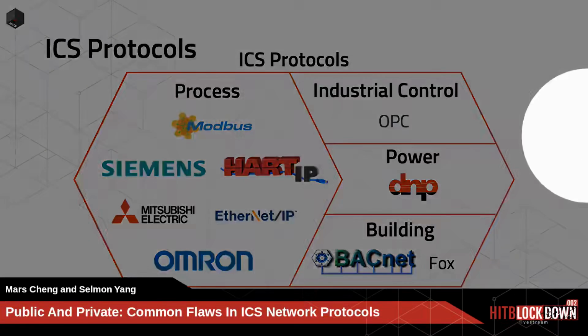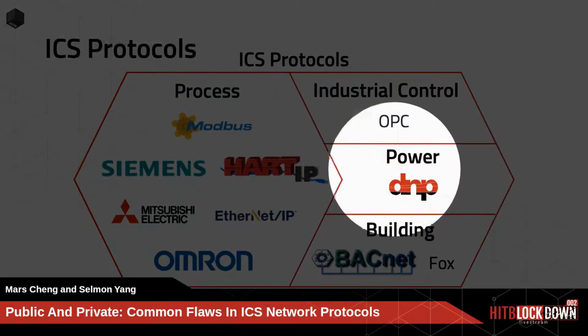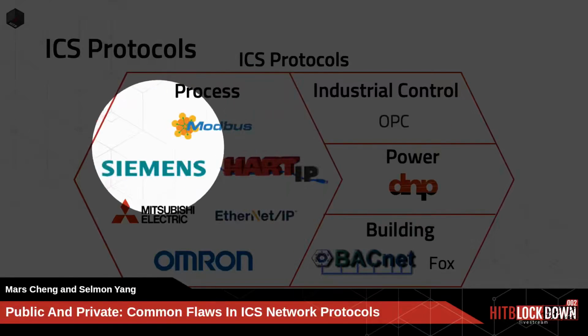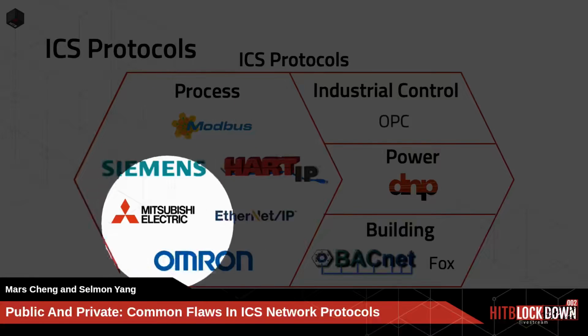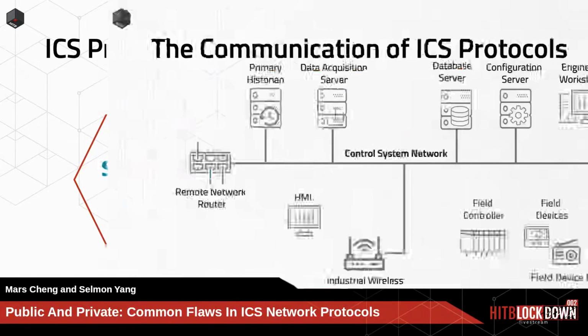Different fields use different protocols. The power industry usually uses DNP3 or IEC 61850, while in process monitoring or process control they use Modbus, Siemens, or some Mitsubishi or private vendor protocols. So many protocols, but protocols are very important.